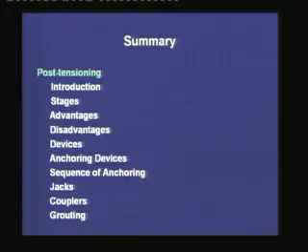Another important feature of the post-tensioning operation is that during the post-tensioning operation itself, the tendons are subjected to the highest amount of stress. That means the quality of the concrete near the anchorage block has to be extremely good, because the end blocks are subjected to high stresses, and unless the concrete is able to sustain the high stresses during the post-tensioning operation, the post-tensioning will not be successful.